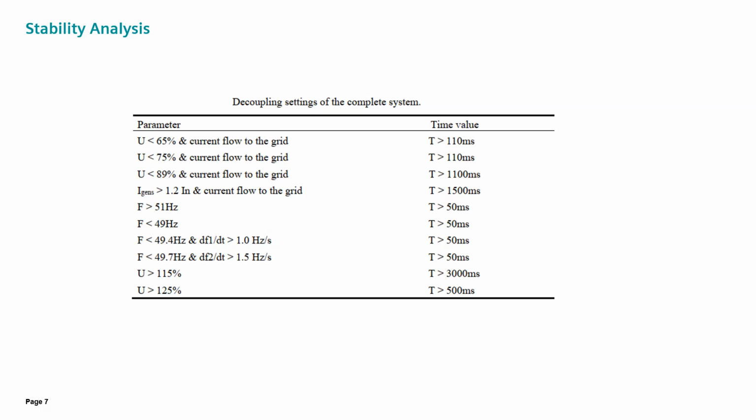In this picture, the reason for having the same disconnecting time for two voltage levels, 65% and 75%, is that the distance protection zones of the network for the second fault stage cannot exceed the minimum time required to ensure system stability. Where possible, separate periods can be foreseen. Those disconnection times from the grid can be optimized depending on the criteria.